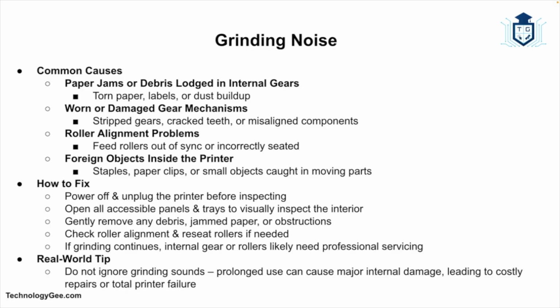Well, you want to power down and open up the printer. Carefully remove any visible debris, and if the noise persists, then the technician may need to replace some internal gears. As a real-world tip, do not ignore the grinding because it can cause long-term mechanical damage.